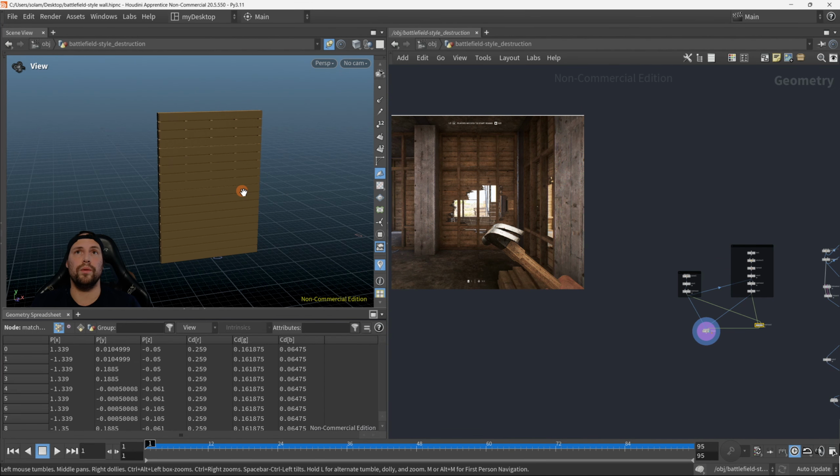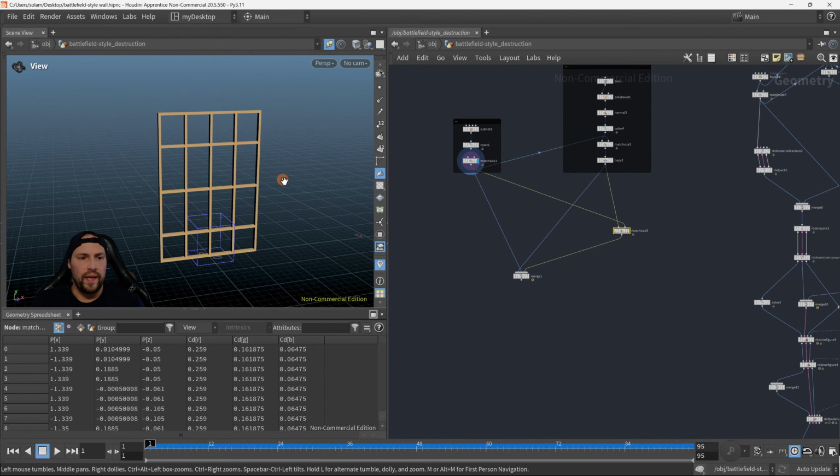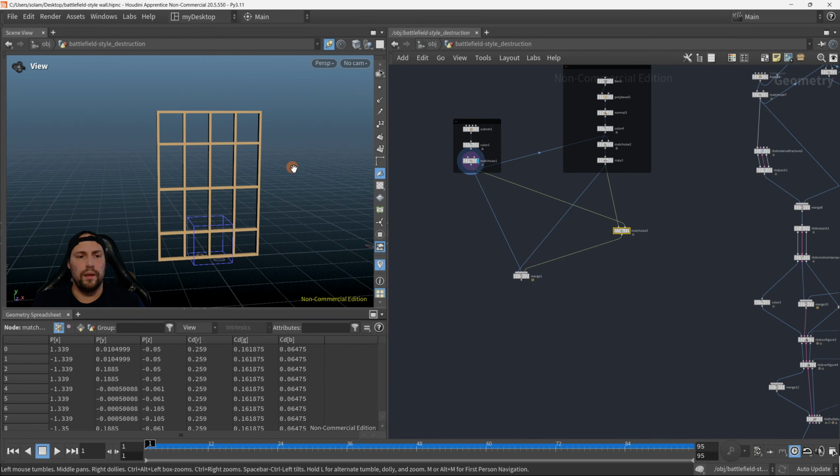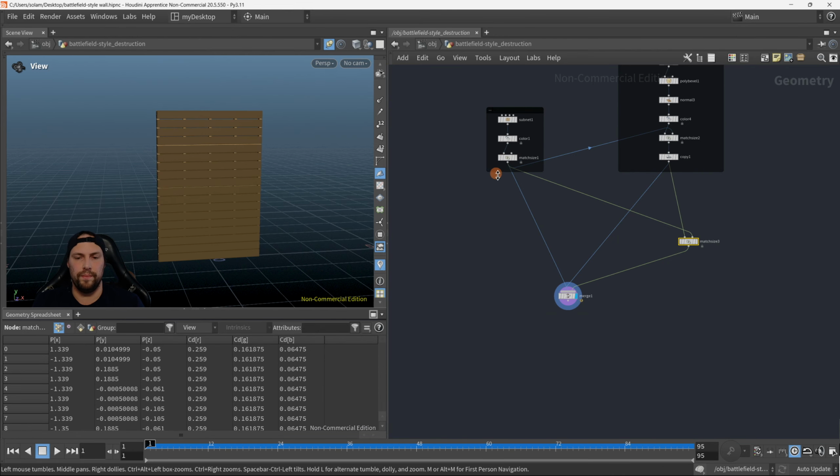You now know how these walls are created inside of Houdini. But this is not going to really work if you want to feed these things inside of an RBD bullet solver. So what we now need is a way to split this geometry apart. I propose we take a frame and make an output of it completely separate from the planks, so we can process the geometry independently.